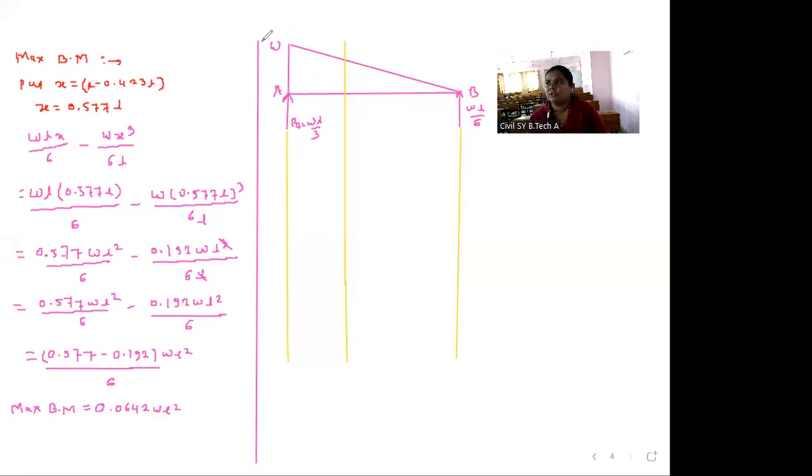So whenever we have done calculations for shear force, at that time x raised to power is 2. So our diagram is cubic parabola. Sorry, only parabola. We will draw first baseline. After that, the value of shear force at A point is WL by 3. So up to this point, WL by 3. The value of shear force at A point is WL by 3.